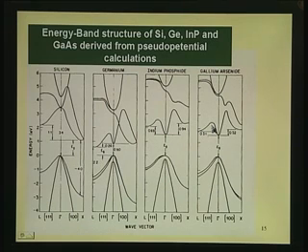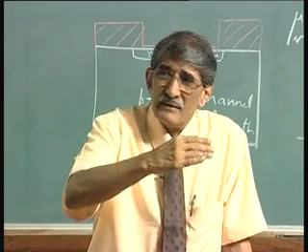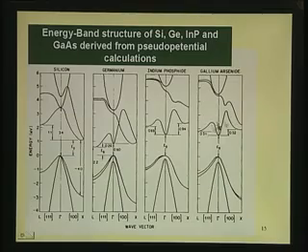So, the energy versus momentum graph in the valence band, valence band means you understand, conduction band means you understand. Within the valence band, how the energy versus momentum varies, that is that bottom curve here. This graph here, this is the valence band. The energy of the electron varies like this. Do not worry about the other lines, because the holes usually in the valence band occupy the highest energy position. The electrons in the conduction band occupy the lowest energy position. So, this is the way the energy versus momentum will vary in the conduction band, and the lowest energy position is this.